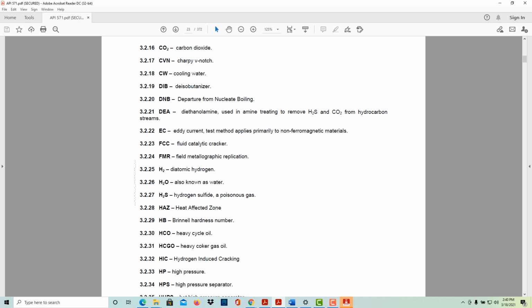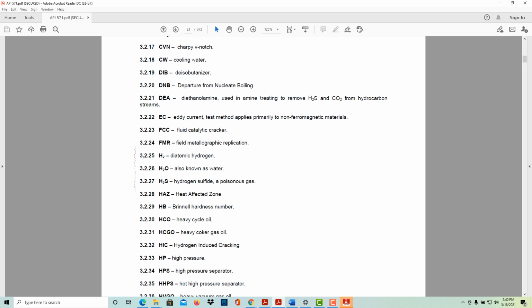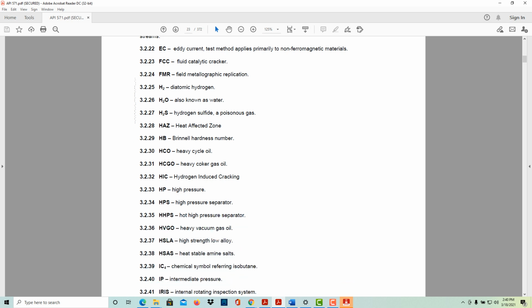EC, eddy current test method, applies primarily to non-ferritic materials. FCC, fluid catalytic cracker. FMR, field metallographic replication. H2, diatomic hydrogen. H2O, water. H2S, hydrogen sulfide, poisonous gas. HAZ, heat affected zone. HB, Brinell hardness number. HCO, heavy cycle oil. HCGO, heavy coker gas oil. HIC, hydrogen induced cracking. HP, high pressure. HPS, high pressure separator.